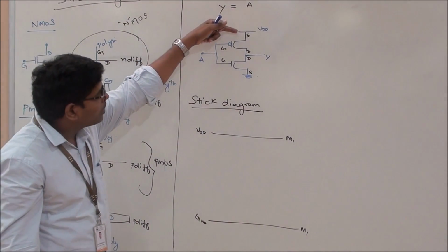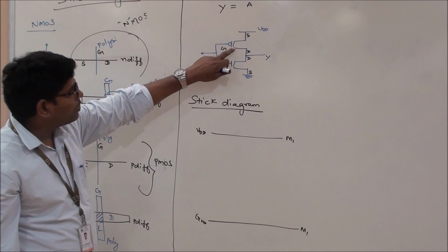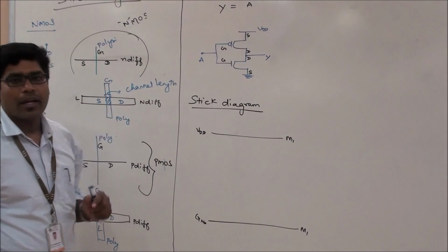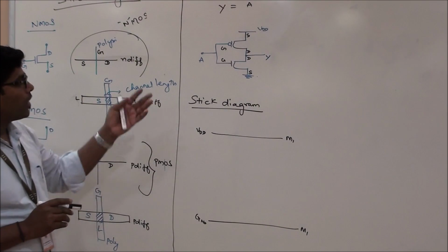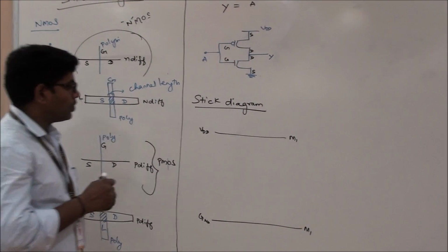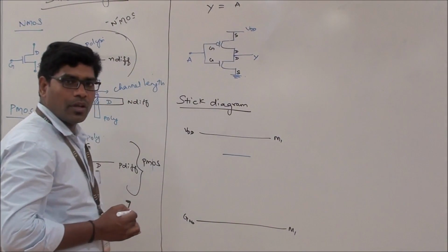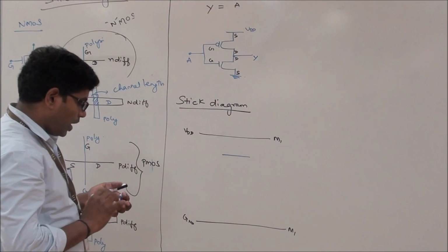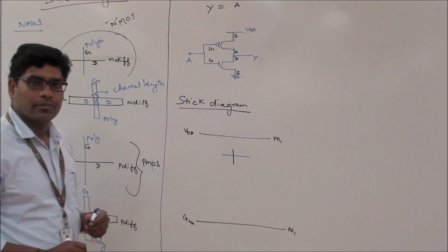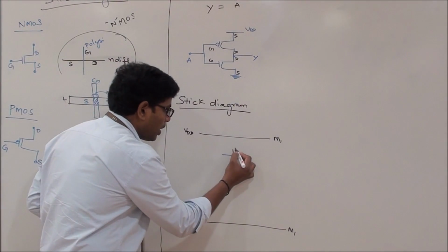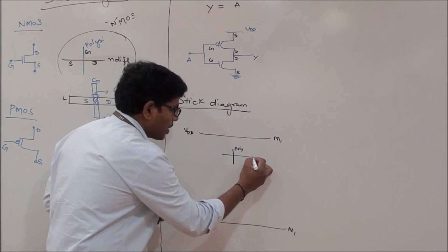So we have finished the VDD and the ground information. The next thing, I am supposed to get this PMOS and this NMOS. How do we get a PMOS? To get a PMOS, you draw a P diffusion, and over that you need a polysilicon. So this is my poly, and this is my P diffusion.